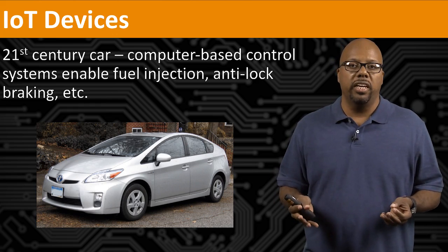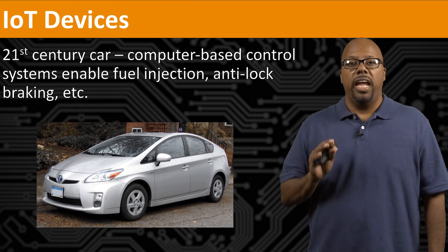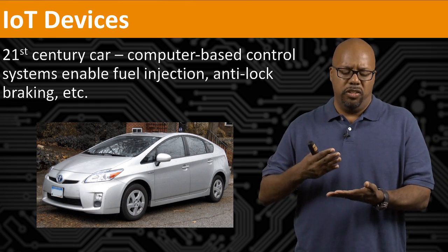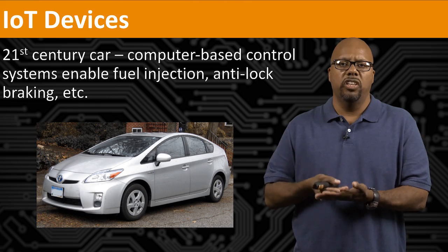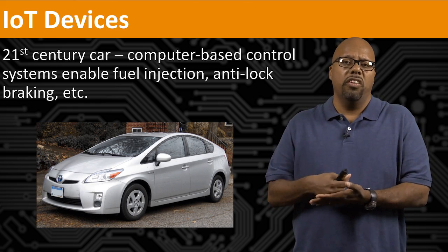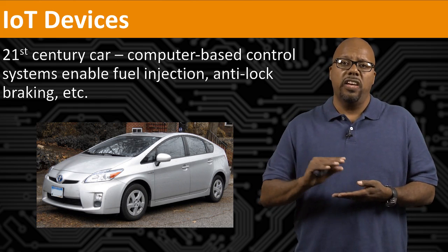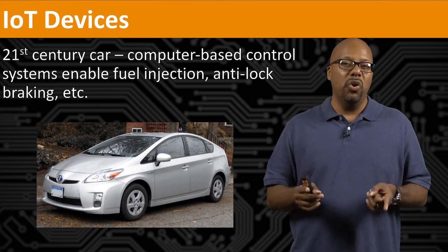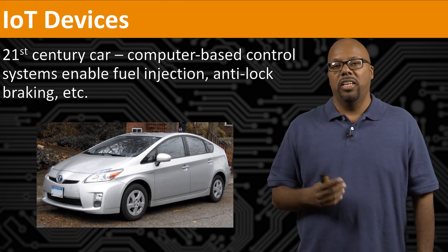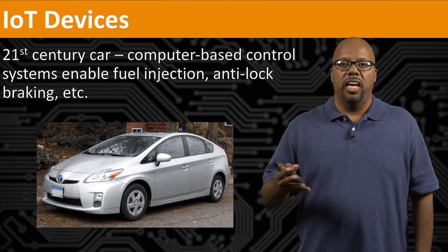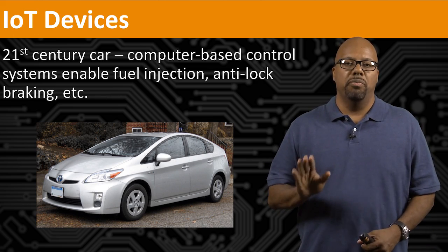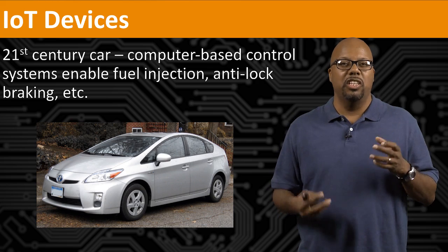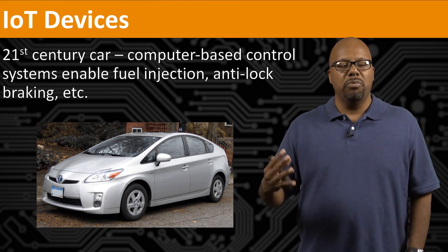So now you have anti-lock braking, for instance. Anti-lock braking, in case you don't know, prevents the tires from locking. You don't want the tires to skid compared to the road. They should always stay in good contact with the road. But if you're moving fast and you brake hard, the car will skid and the tires will not move, but the car will move. So anti-lock braking tries to prevent that. Before anti-lock braking, I remember when I learned how to drive on snow, you skid a lot. So when you do a hard brake, you'd manually pump the brakes. And you'd have to remember this. You have to be pretty consciously aware to remember to do this. Anti-lock braking does that for you.